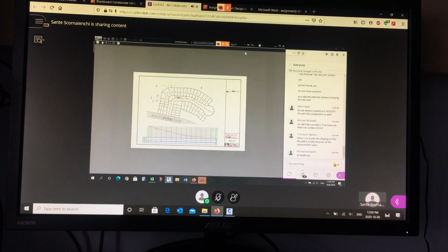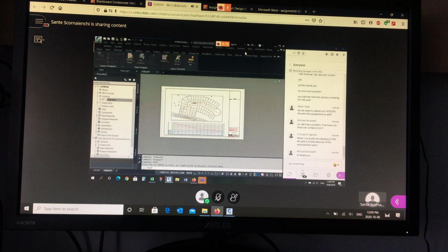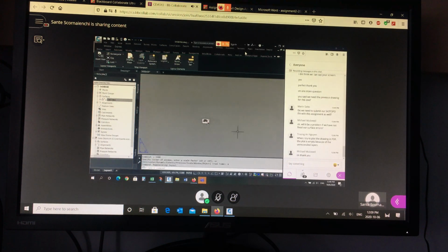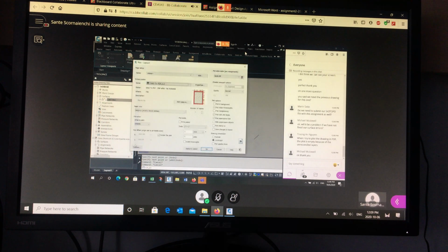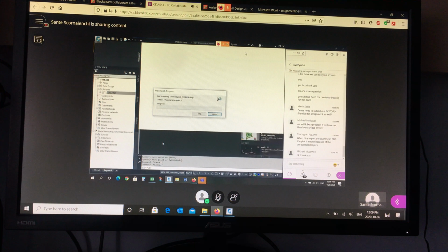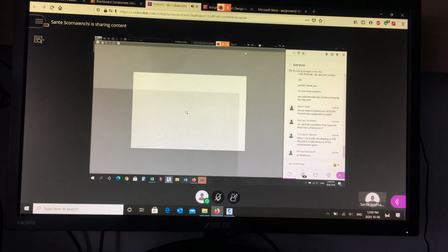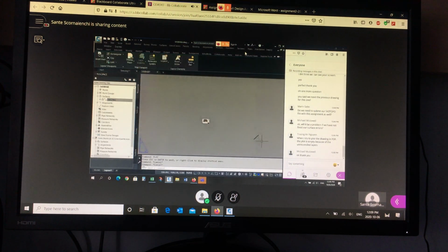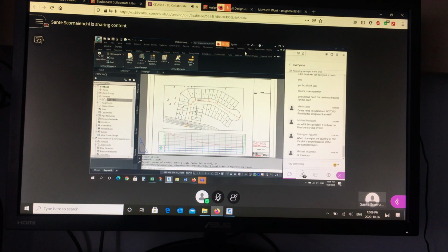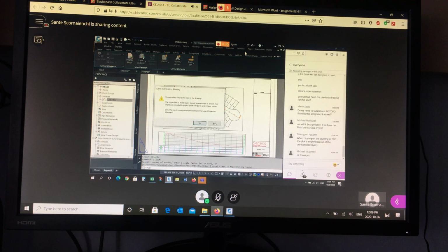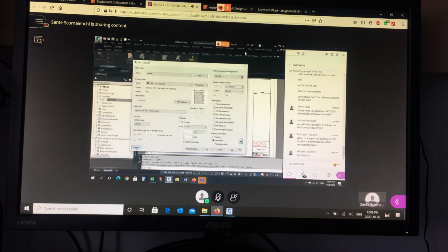If you don't see stuff, if you zoom extents, and you have some line out here, and you go to plot and say preview, because this says extents, it's going to look like this. It's a problem. If you have what I call space junk, something out here outside the frame of the drawing, you could end up with that effect. So I want you to erase anything that's out here. If you zoom extents and it fills the window, when you go to plot, it should fill the sheet.